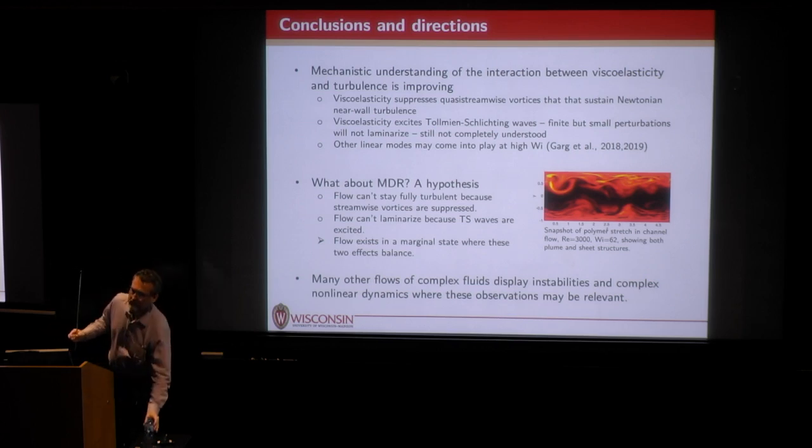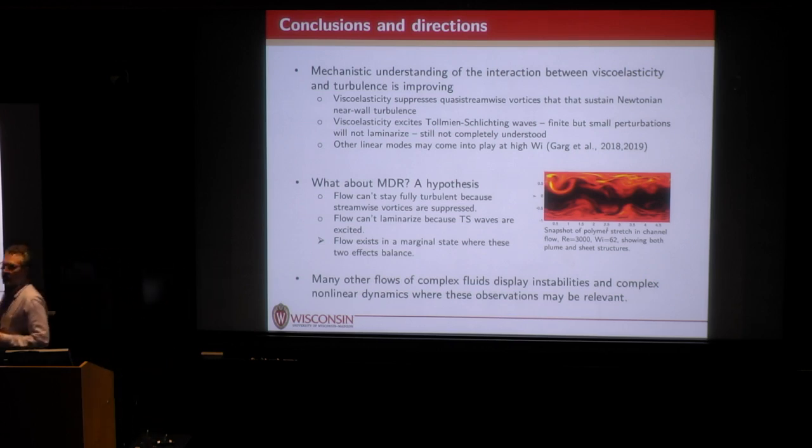Just another quick one. What's the initial amplitude with respect to the centerline flow for this nonlinear traveling wave? Oh, in the velocity, they're very, very small. It's really quite striking how small a perturbation is necessary to move you away from laminar. So the laminar is linearly stable, but the linear regime is very, very tiny.